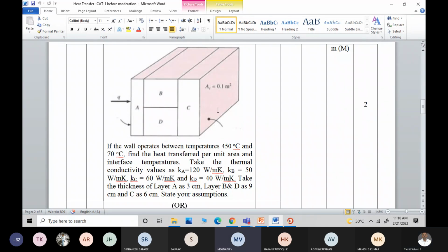The heat is transferred along the x-axis direction, and there is one person who asked me whether you have asked to find the temperature at the midpoint between B and D. No, I said no. See, the x-axis direction only we are considering. One-dimensional heat transfer, dou square T by dou x squared. You are differentiating it twice and you are getting the solution temperature.